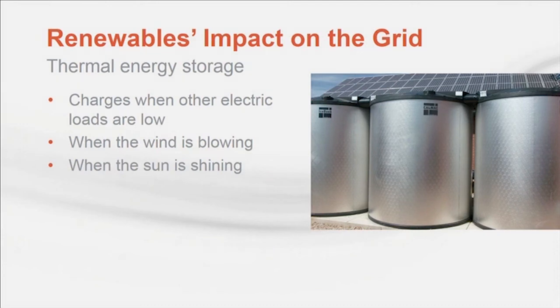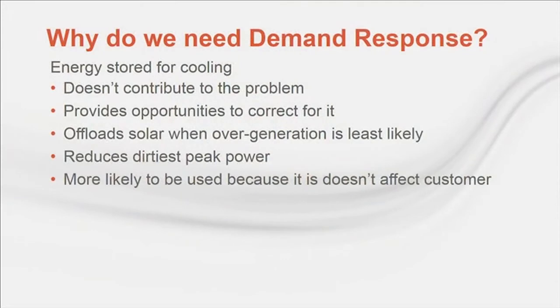It's important to realize that the duck curve we just looked at came from March in California. It doesn't reflect much cooling demand. The shape of the net energy curve in July and August will be much different. Now, solar likely does coincide with midday peak usage in the summer, thanks to air conditioning. Thermal energy storage for air conditioning is helpful in a number of ways.